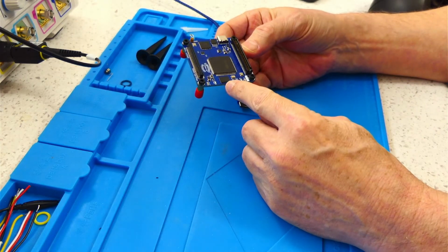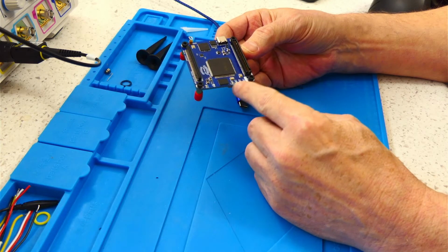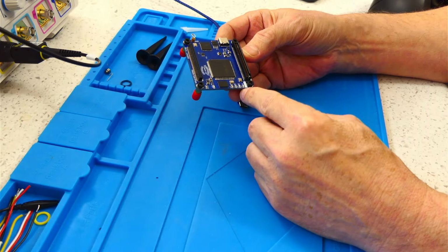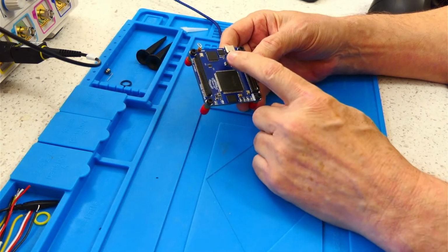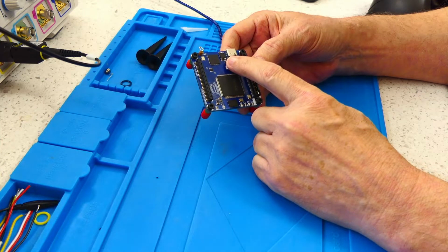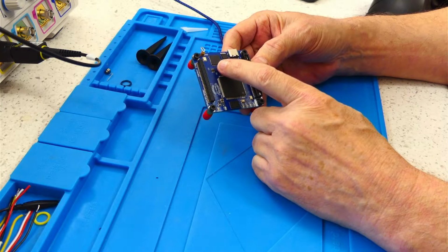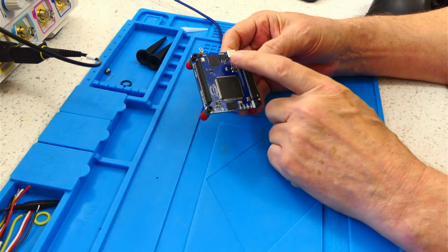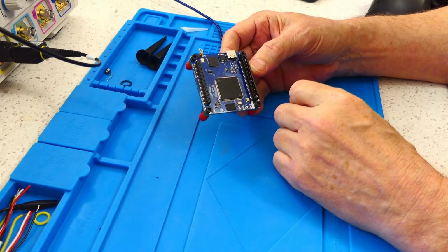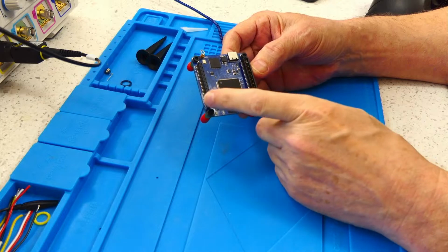This also has 16 megabytes of HyperRAM right here with 4 LEDs. I'll use 2 of them for locked and no lock condition for the phase lock loop. It has a SPI flash right here for the bit stream that the FPGA uses to configure itself, and a FT4232 quad high-speed interface chip for interfacing to the SPI flash. Also has a JTAG interface that goes to the FPGA and 2 additional serial ports that are interfaced to the FPGA and routed to the bus system.